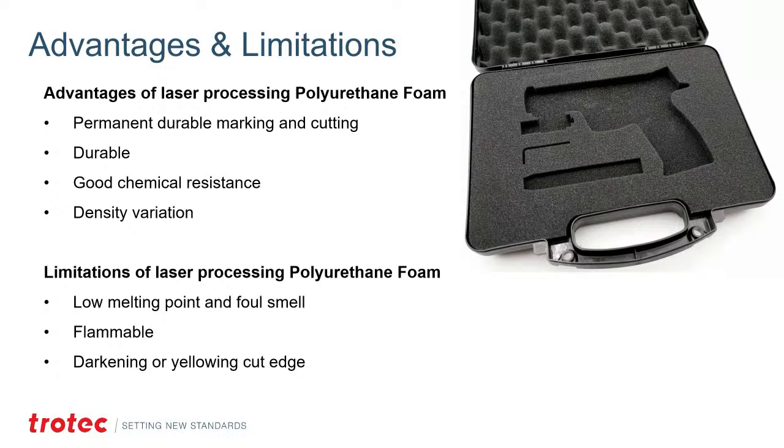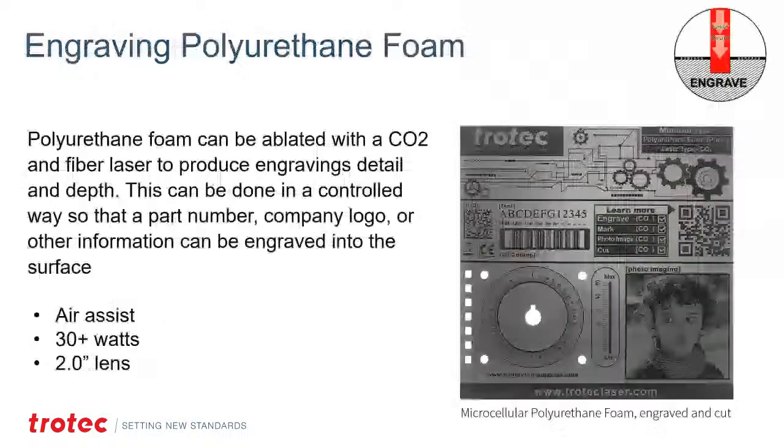You do, of course, also have a little bit of a darkening or yellowing cut edge, as I mentioned earlier, so the grayer foams work much better. And this material is very flammable, so you want to keep a very close eye on it, especially if you're cutting it. Thicker materials, if you don't have enough wattage or good enough air assist, this stuff can ignite very quickly and get away from you. So keep a very close eye on this material should you decide to cut it, especially thicker materials.